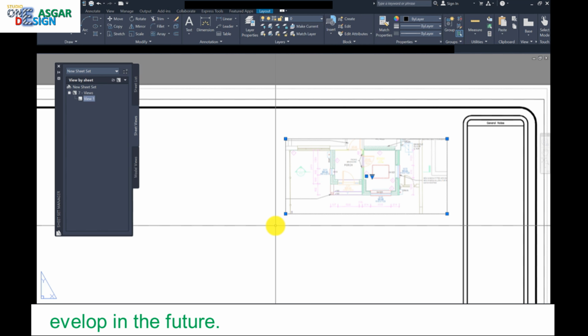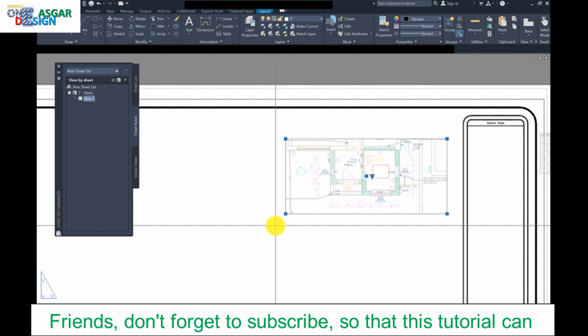What we're also able to do now is add dynamic tags. We have a good understanding now about what dynamics are. Earlier, when we created our dynamic block, it allowed us to manipulate the windows and doors so we could stretch them, rotate them, and so on. What we can also do with the dynamics within blocks is label things. Right now this is our view 1 on our view sheet, so we can add a label which will automatically display that information.